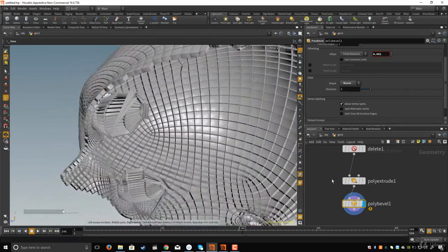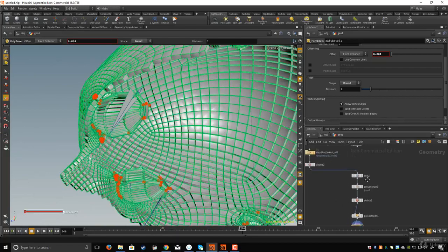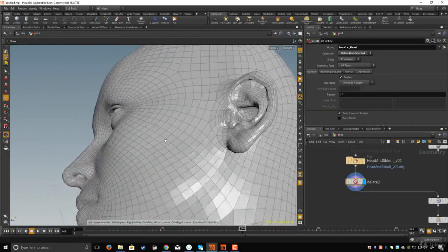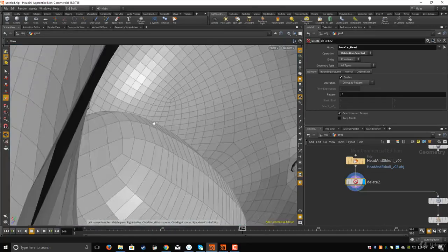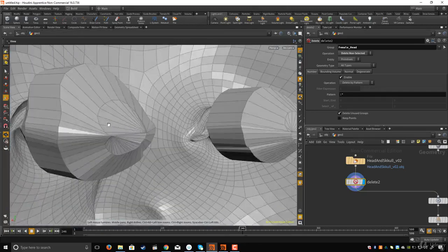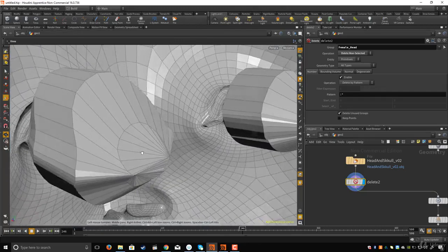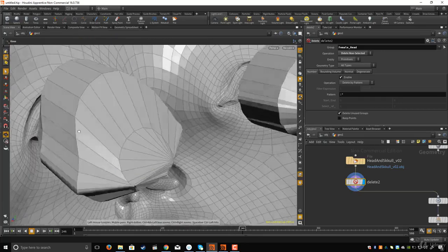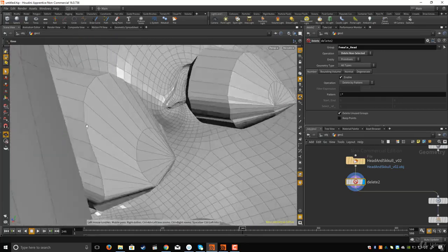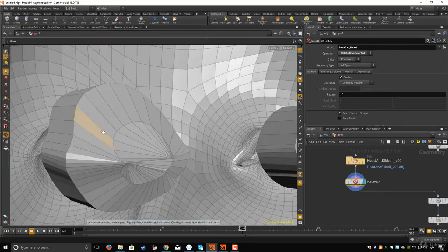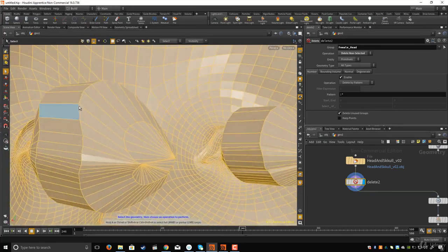We can fix that in another way too, guys, by coming to the delete node here, and I will go inside and delete these eyes, this inside eyes. So I can click on select and select the eyes by coming here.